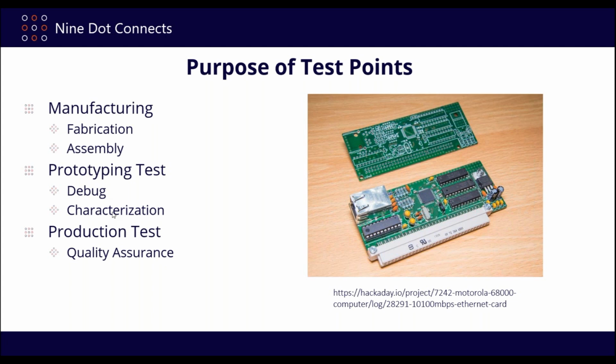It means that now you're probably going to have to characterize it. Well, yeah, it did work at this voltage. Can it work at a higher voltage? Can it work at a lower voltage? Can it work in different temperature settings, for example? Like if you're doing military grade or avionic grade, they may be doing shake and bake or vibe or some other type of harsh environment testing on this to make sure that it's going to be able to withstand pressure or temperature or whatever else is being inflicted upon it, moisture, for example.